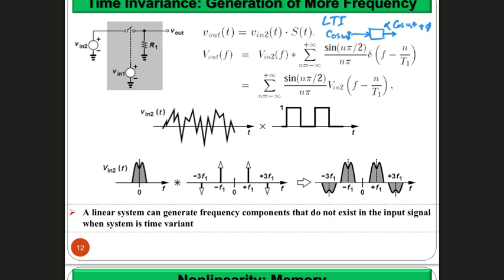You know from your signals and systems that this will look, regardless of the values of the amplitudes and everything, like the Fourier transform of the square multiplied by a train of impulses, and those impulses exist from minus infinity to infinity. Okay? So this is what it looks like. The sinc, which is the Fourier transform of the square, and then multiplied by the train of impulses at different frequencies, right?